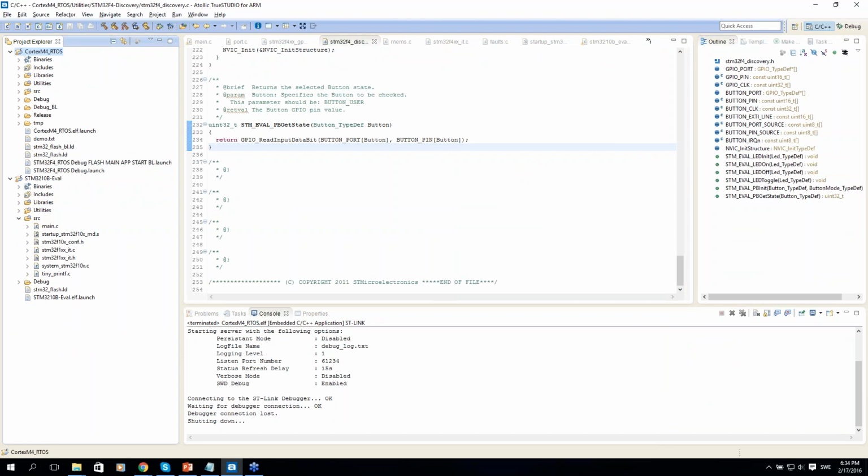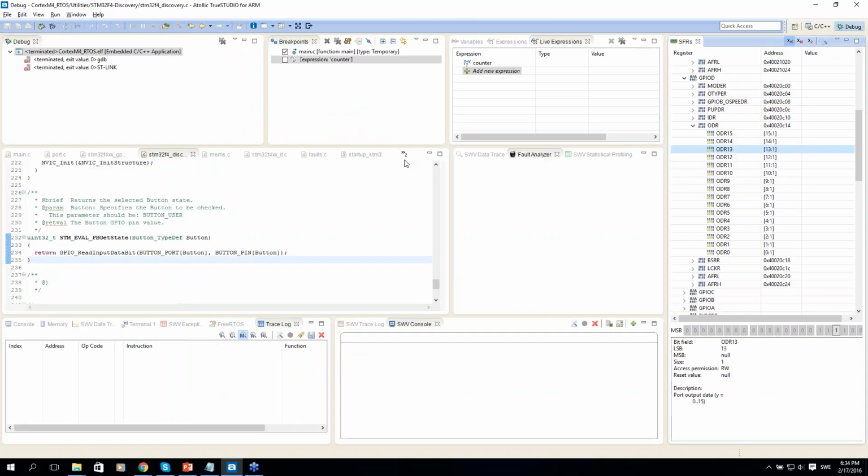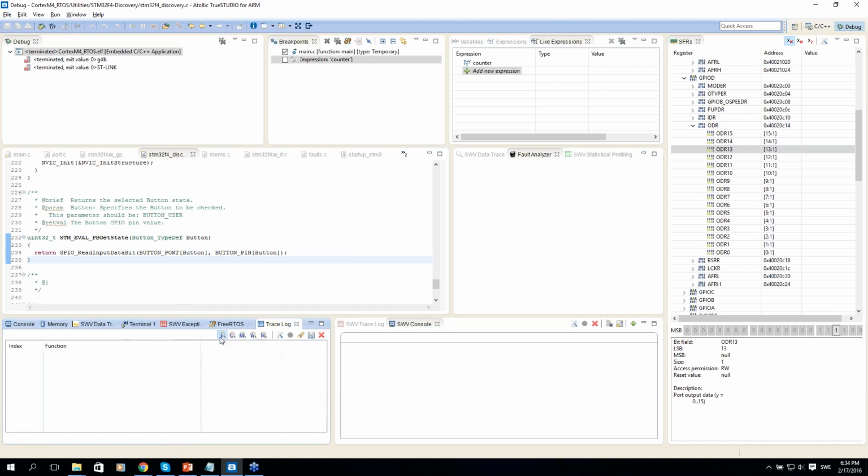Okay, well, I can't demonstrate it without hardware, a Cortex M3 or M4 microcontroller that has the ETM module as part of the core, and I don't think my board has that here. What we can say is this. As you've seen, we have this view to visualize data. If we use this representation, you will see function call nesting. So which function called which and how did we return? That's how that is going to be represented to you.